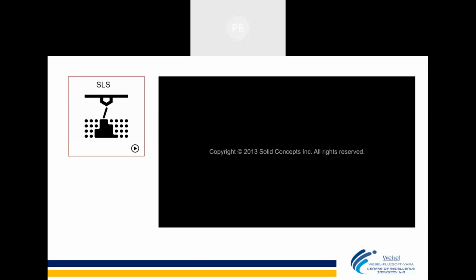So this is a very advanced technology, SLS, with which we can do a certain level of batch manufacturing in a very short time. SLS is one of the technologies which has been invented for batch manufacturing. It can print a short batch, like maybe 100, 200, 500, 600 pieces, within a minimal time, because there is no support development and no post processing time. We can directly take out the part.